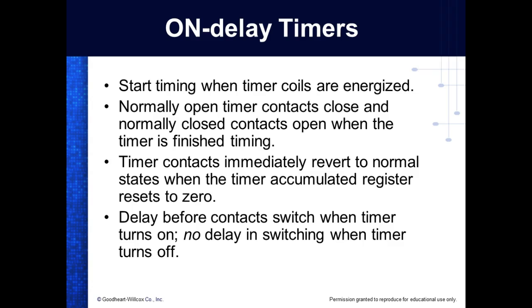There's a delay before the contact switches when the timer turns on, and no delay when switching when the timer turns off. So it's an on delay timer. That means when you energize it, timing takes place. When you de-energize it, the contacts change back to their original state instantly, right? Y'all understand that?